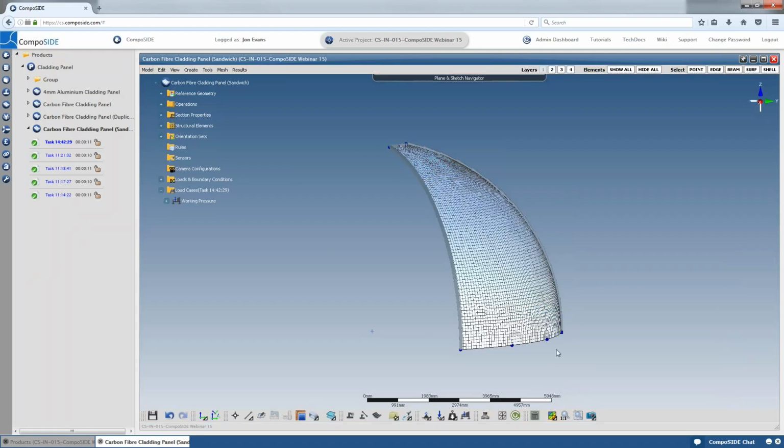So before you go to that task, so basically what you've done, you had a design in aluminium. Yeah. And you've basically using the same model, basically swapped the aluminium for a single skin option, keeping the intermediate stringers, yeah. And also then looking at a sandwich solution just by swapping the laminate, using all the same analysis setup and jumping in and out of FE space and interacting with laminar space. Correct, yeah. Okay.